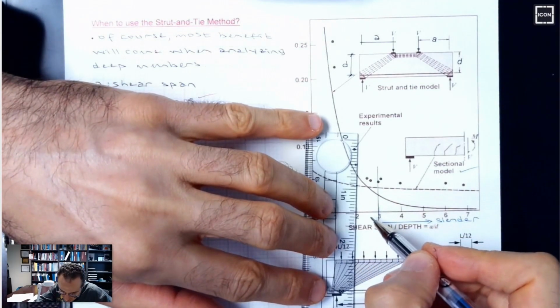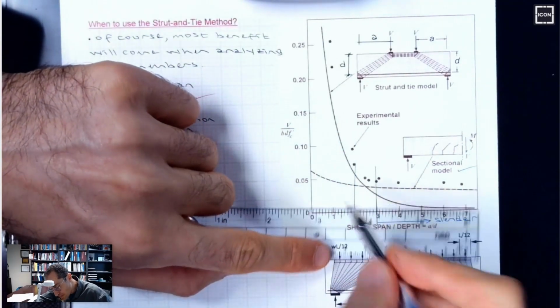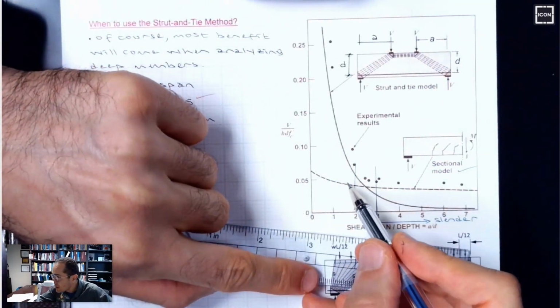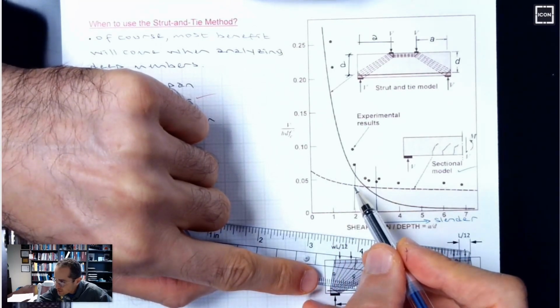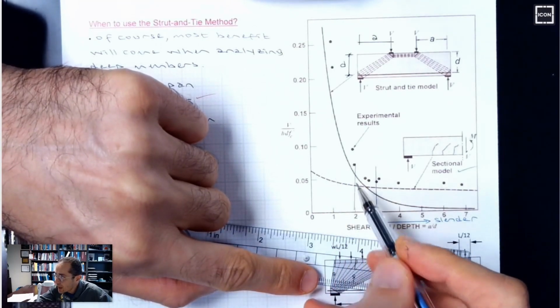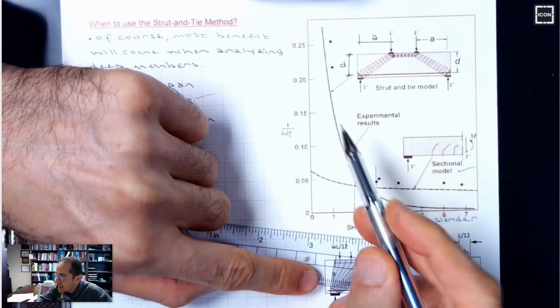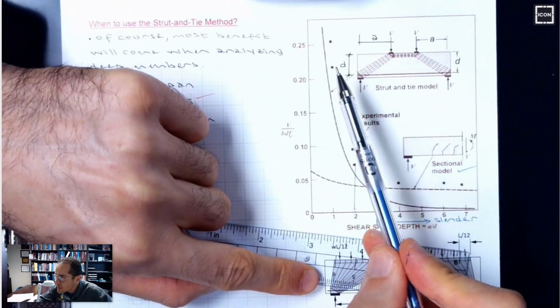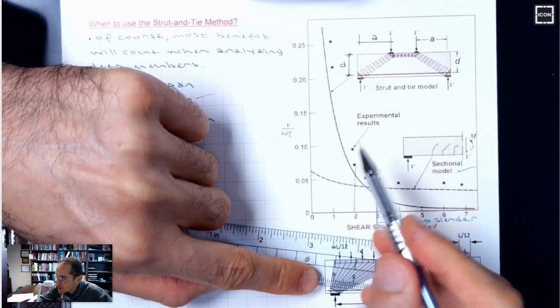In the 2 to 3 transition zone, as I said previously, but less than 2, the sectional method will really give you a fraction of the capacity. You can still use the sectional method. It's not valid, but it would still give you some result. The real capacity would always be larger. So the deeper the member, the discrepancy will increase.